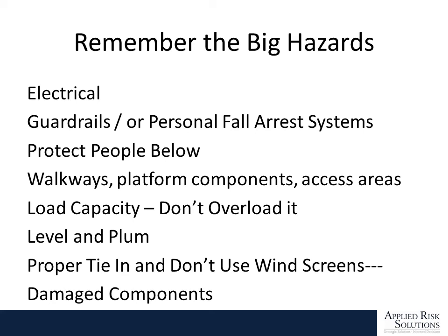You must be very careful with this. It's easy to do. You design it to put so many bricks up there or so many rocks or whatever it is you're doing, and it's not communicated to your workers, and all of a sudden somebody sets something up there and they're way overloaded. Be sure everything is level and plumb. That's critical in setting up scaffolding. Be sure you tie in properly. Don't use windscreens, and don't use damaged components.